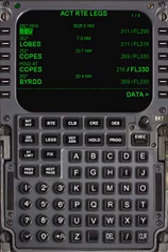Implementation of an accurate VNAV is difficult and expensive, but it pays off in fuel savings primarily in cruise and descent. In cruise, where most of the fuel is burned, there are multiple methods for fuel savings. As an aircraft burns fuel, it gets lighter and can cruise higher where it is generally more efficient. Step climbs or cruise climbs facilitate this. VNAV can determine where the step or cruise climbs, where the aircraft drifts up, should occur to minimize fuel consumption.